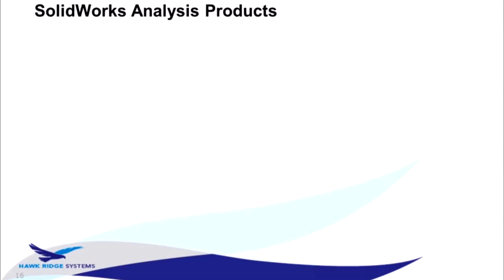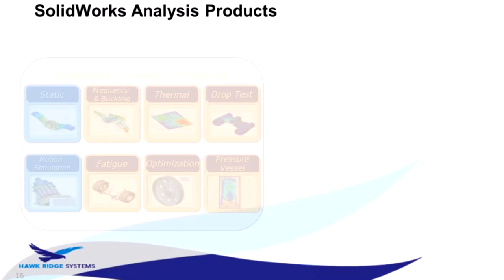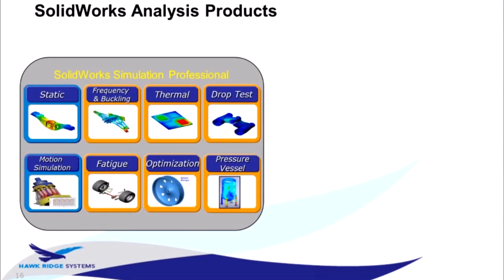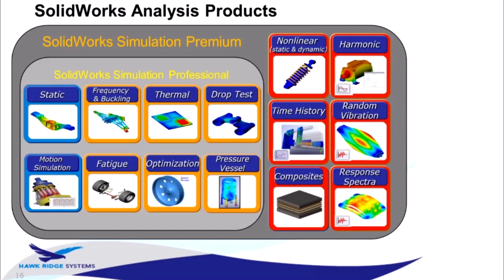But what we're going to focus today's presentation on is the simulation static analysis type that's part of the SOLIDWORKS Premium CAD bundle. It's the blue bubble over here called static analysis. 80% of the stress analysis that's done today is done right in that module. We do offer other analysis capabilities. Our Simulation Professional package introduces frequency and buckling, some thermal and optimization routine. A Simulation Premium package offers nonlinear and dynamic analysis.